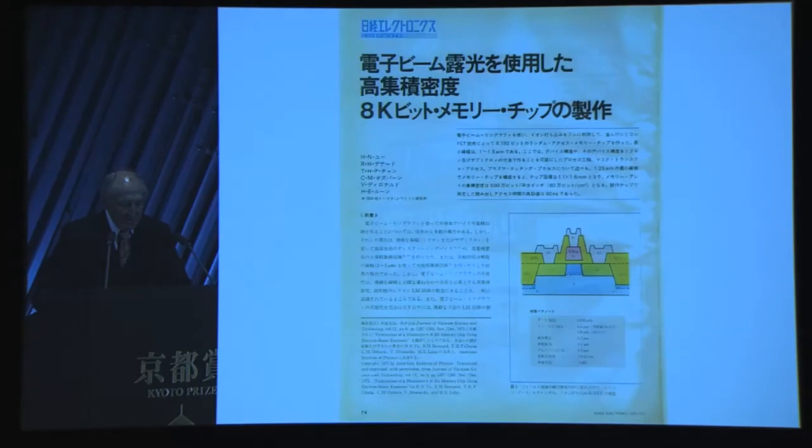Circuit design and innovations also played an important role in the development of the dynamic RAM. The main difference between the dynamic RAM and the earlier static RAM was the need to sense very small signals coming from the memory cells onto the bit lines when a given word line was activated, and to write the original voltage levels back into the memory cells after this destructive read. For some time after my invention, I had the notion that I could use off-chip bipolar sense amplifiers like we had used with our previous static RAM chips.